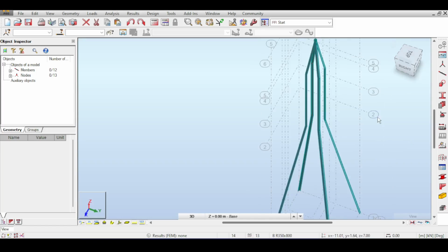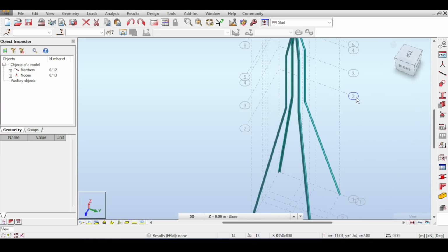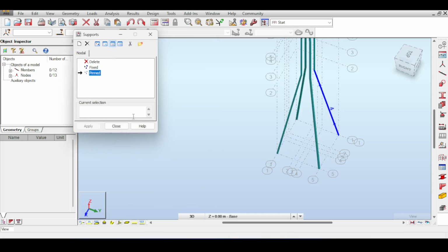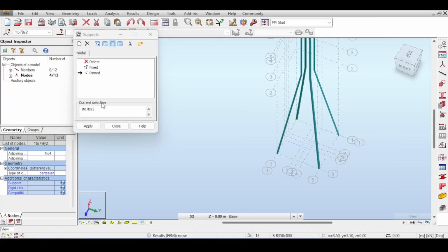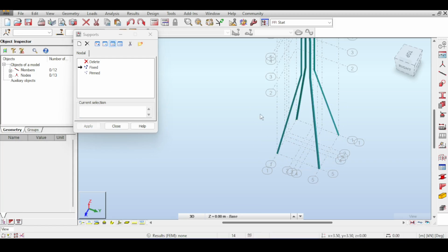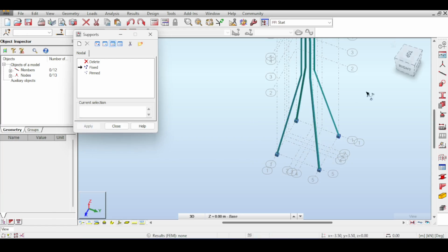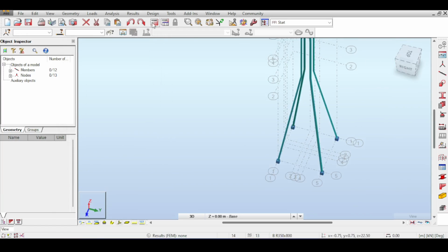So now we're not finished. We did just one little part of the structure. Now, I have a modus operandi where I like to keep checking the structure. So I just pin everything. As a matter of fact, I assume it's fixed because I want to stiffen it. Now, by the way, if you assume it's fixed, you're assuming that the foundation doesn't rotate. So I'll assume it's fixed for now, and then later I will talk about the foundation if need be.